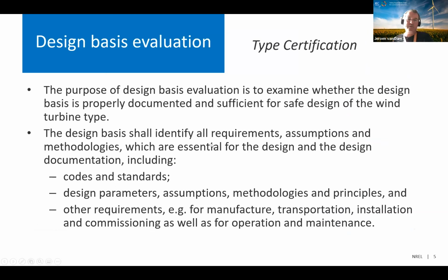The design basis evaluation, so that was that first building block we saw at the top. That's really to define what we're going to do. So what are we certifying, and what are the standards we're going to use? What are some of the design assumptions? So what wind turbine class are you going to certify to? How are you going to do that? So I see this really as a certification plan to some extent. What are some of the materials you use, load factors you're going to assume? In this case, since we are in the large turbine category, simplified load models are not acceptable here.